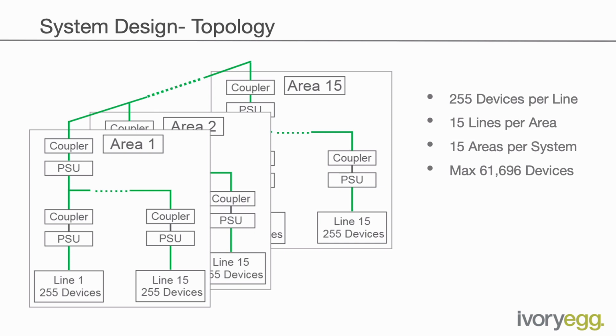If you've got just a keypad and maybe an 8-channel relay, and you need a small power supply, those 3 devices are all you need in the system. If you want to increase the functionality or increase the size of the project, you just add the devices you need, which means KNX is applicable for loads of different projects. It could be small residential, it could be commercial, it could be offices, it could be medical, used in hospitals. It is very, very powerful in that sense. And the topology ensures that you get the most amount of reliability and resilience built into the system.